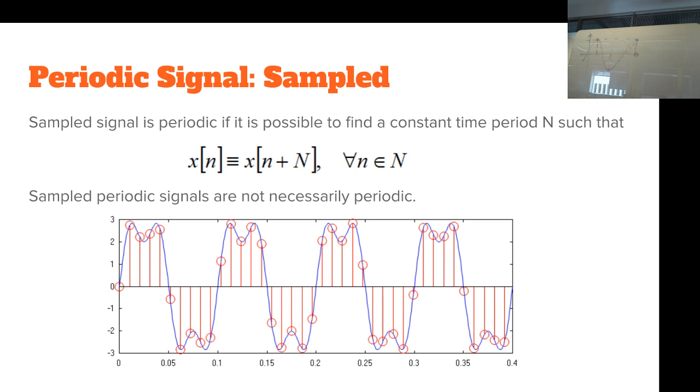Only in the case that you have exactly matched those sample points, for example like that, but that has to be exact, will you see a single peak on the spectrum, which practically never happens. You don't have such luck unless you are measuring the internal oscillator of the oscilloscope. Otherwise you get more or less envelopes on the spectrum analyzer.